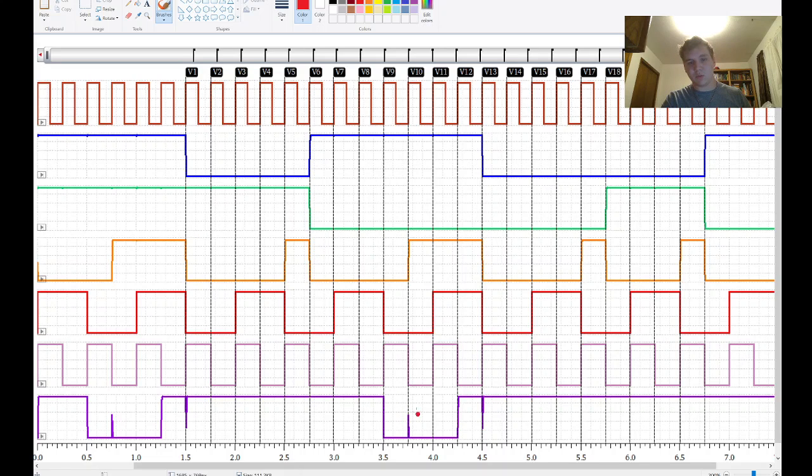This logic hazard here unfortunately did jump up to be high when it's supposed to be 0, but we saw that generally all these are 0 as they should be, and so this logic hazard really did not affect anything, because the circuit still carried on normally. It still carried on how it was supposed to.